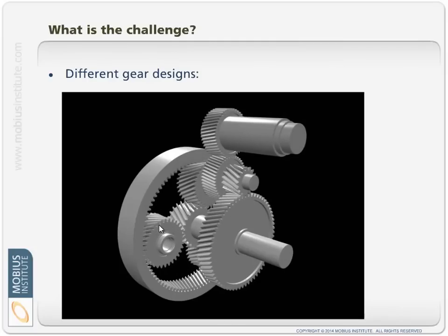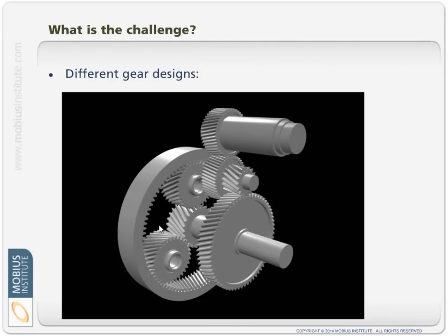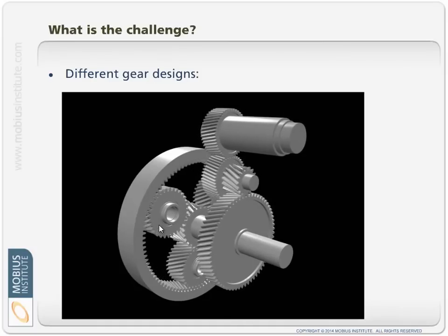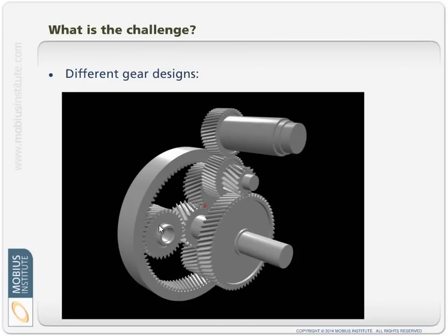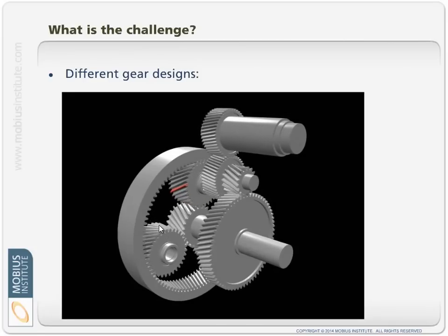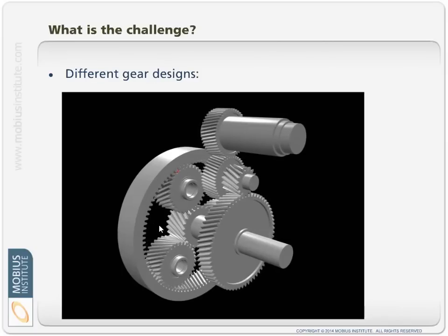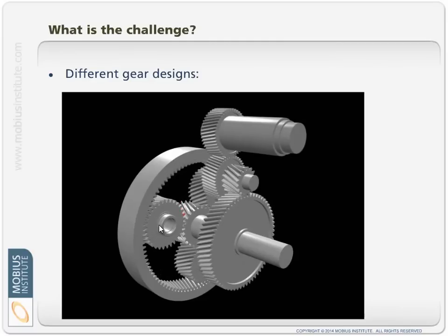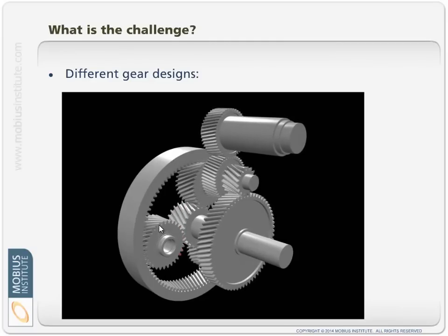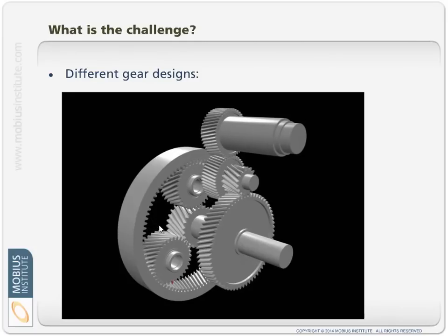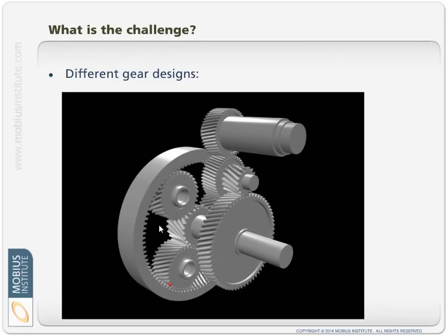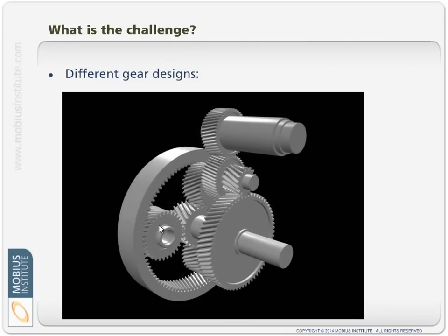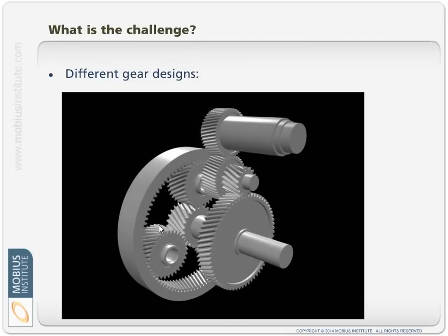As with everything in vibration analysis, sometimes you have to make compromises. You'd prefer not to, but in this particular instance with a planetary gearbox in a wind turbine, you may not be able to mount as many accelerometers as you might like. In a case like this, you are most likely going to be permanently mounting the accelerometers, and probably permanently monitoring the system as well. But if you understand the design, you understand all the issues related to detecting gear faults, then you can make the appropriate choices.